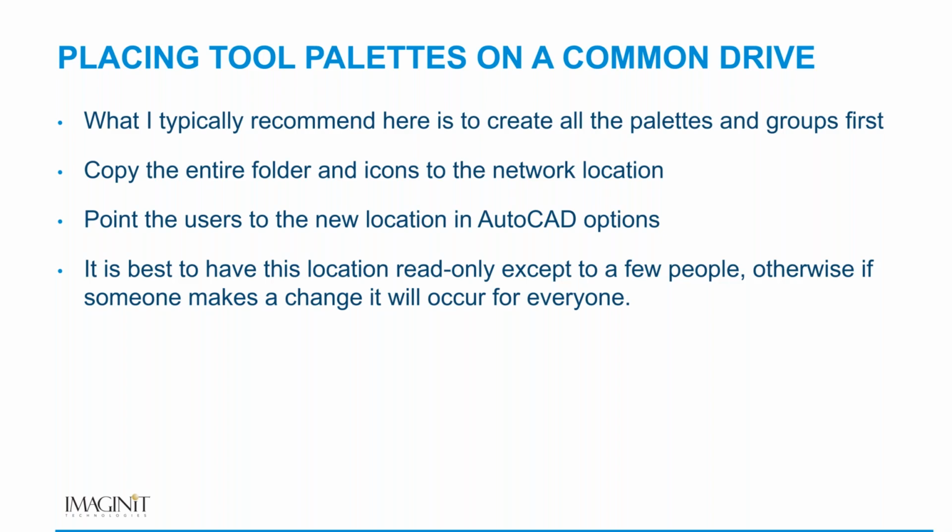Is there a setup for using a replicated drive across multiple offices? We haven't been able to get it to work. No. Running DFS or replication is going to be very difficult to get to work, simply because if someone has AutoCAD open and they have the tool palettes open, the replication fails. And then you get those tool palette or asset was open by so-and-so, tool palettes get created. Your best bet is, if you're going to be doing that, to only do that.